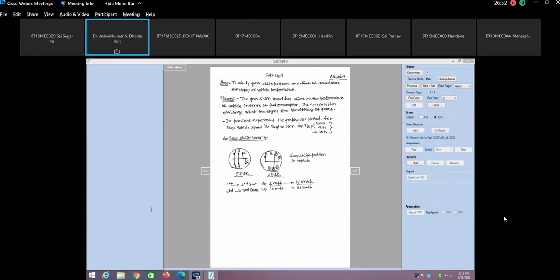then you realize that you don't require that much torque. Almost at the time when the vehicle reaches 15 to 20 kilometers per hour, you feel that you have an excess amount of torque, which is not the requirement, because once you start, the torque requirement goes down. Then you shift the gear shift lever. So that is the speed. That means from 0 to the first gear, when you start from 0, it should be 0 kilometers per hour to 15 kilometers per hour.